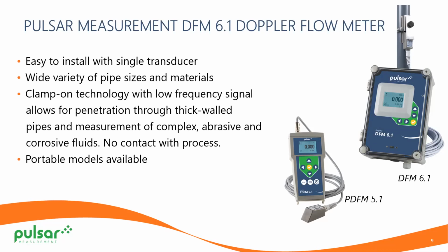Again, the clamp-on technology with a low frequency signal allows for penetration through thick-walled pipes and measurement of complex abrasive and corrosive fluids. No contact with the process. Also, portable models are available, and I should have said that about the transit time as well. We have portable versions, battery powered, for both the DFM, the Doppler, and the transit time. Our fixed models are also available in DC power as well.